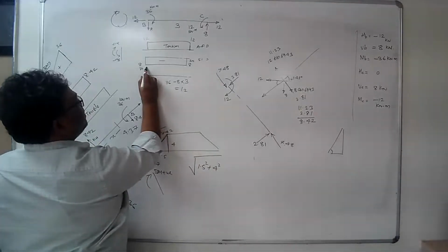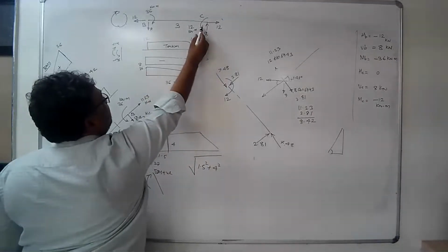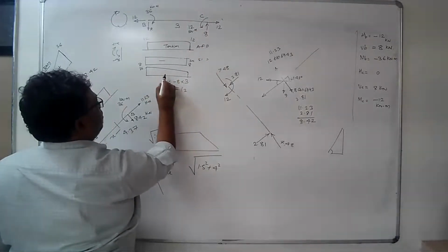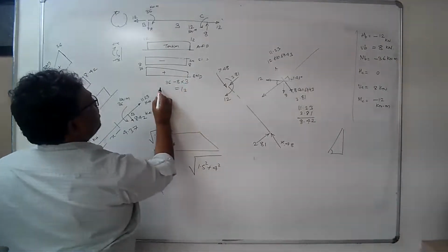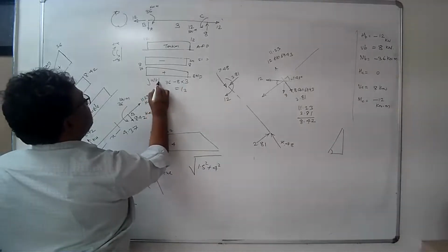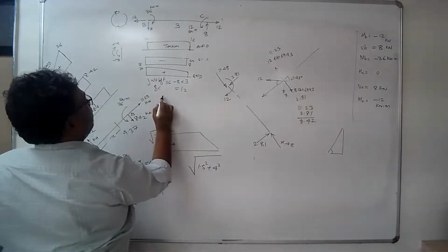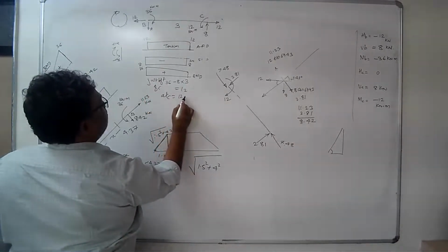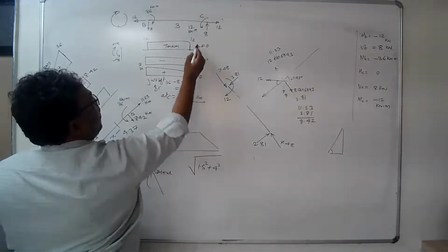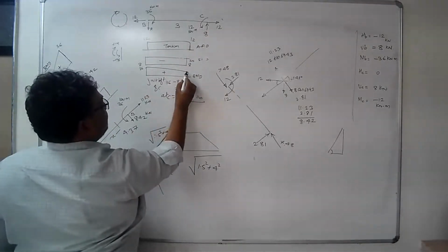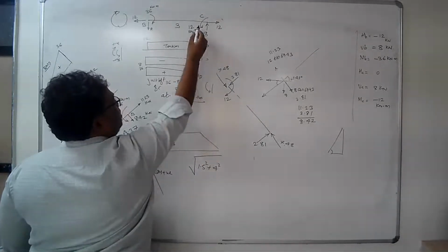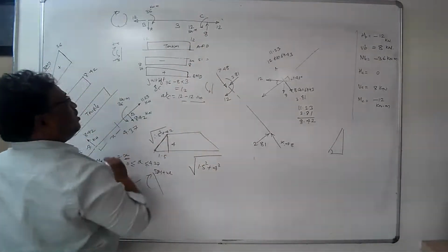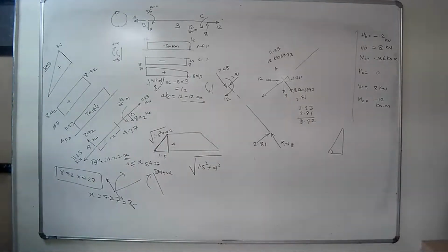तो यहाँ पर 36 है, यहाँ आते आते 12 हो गया है, then this 12 is down, so it will come to 0. This is positive. This is the bending moment diagram. It is just at left of C, or at C it will be 12 minus 12 will be equal to 0. यहाँ पर 12 है, तो यहाँ तक आने तक ये पॉजिटिव 12 रहेगा, then this is minus 12. सी देखिए ऐसे है, so this is minus 12, so that will come to 0. This is the bending moment diagram.